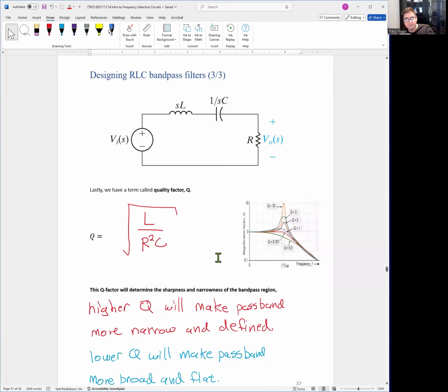After designing it, some people came back and said that the filter is too flat sometimes, or too spiky. Like you saw in the previous graph, one was kind of flat, one made a pretty big dip and came down. So there are different arguments: maybe we want a flat one, maybe we want a very spiky one. So there's another quantity we could play with called a quality factor Q. Quality factor Q is basically how sharp of a rise you want your bandpass filter to have.